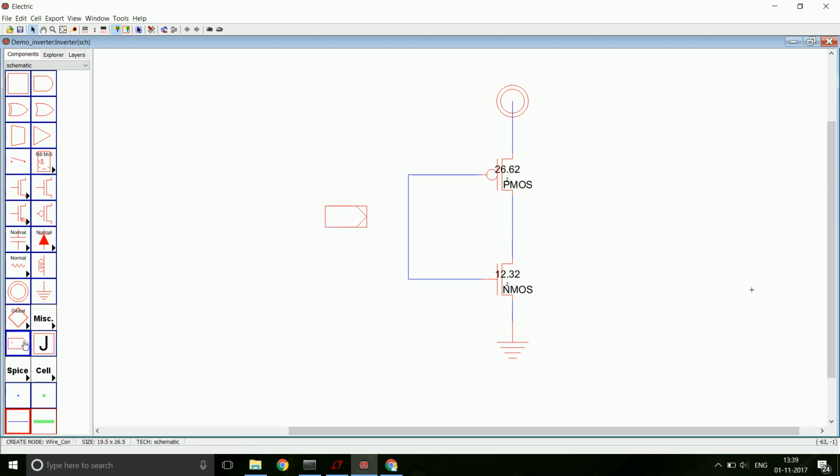Input and output. Select the rightmost part of the input port with a left click, connect. Similarly, left click, connect. So we're done. These are the different components of the circuit as you can see. Now there's a certain thing called export, so we need to name these ports with whatever names we want to give them. Select any port and press Control E.